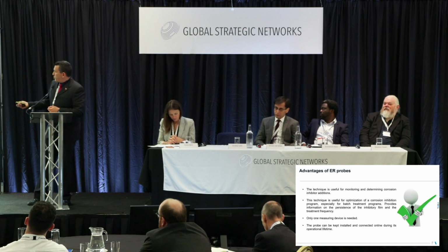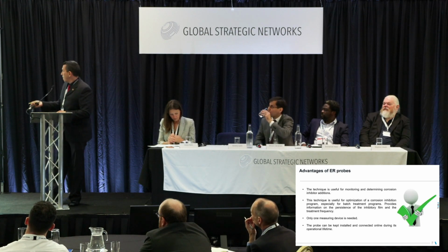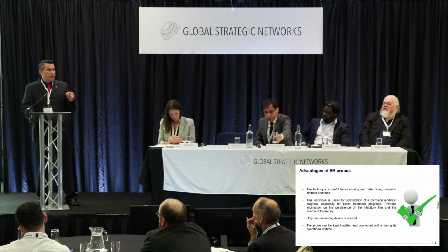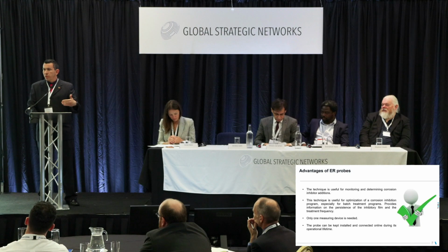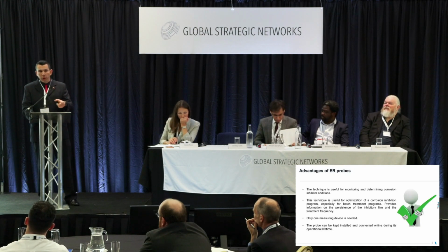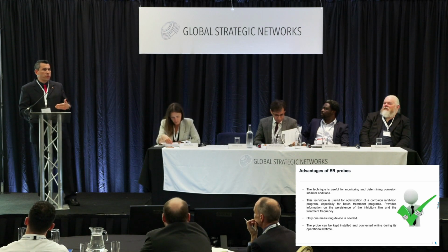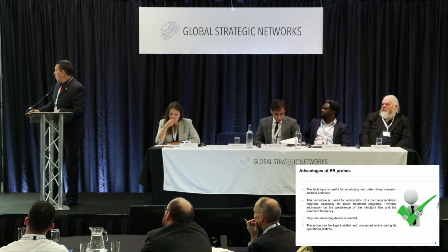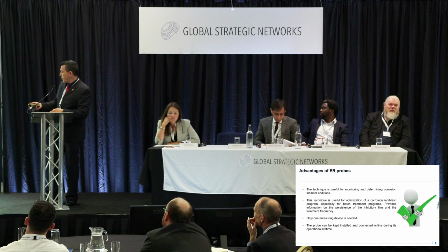This technique is very useful for monitoring and determining corrosion inhibitor additions, as I already explained, because if you have the thinnest type of probe, you can batch or you can inject your corrosion inhibitor, and you can notice the change in a couple of minutes or hours. You don't have to wait weeks or months as you do with corrosion coupons. Only one measuring device is needed, and the probe can be installed in the system until the end of the operational lifetime.